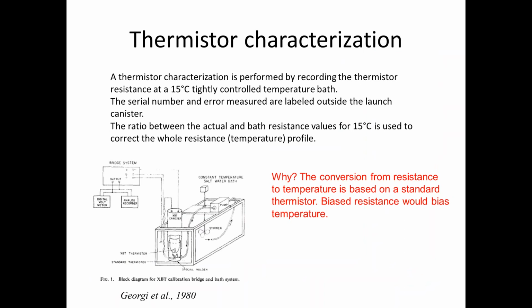So in the thermistor characterization, the manufacturer puts the probe inside a water bath and tightly controls it at 15 degrees Celsius and sees what the probe registers and what the standard one registers. And that difference would also generate a bias in temperature.